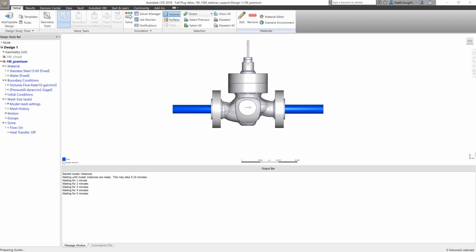Okay, so we are starting to see some questions. So do we need to worry about large element counts, and is there a restriction of RAM? The reality is we already have a really high amount of RAM for the workers on the cloud, and I haven't seen a lot of restrictions on element count, but there eventually would be, right? You're going to run a 100 million element model. It may or may not run on the cloud, depending on the mesh and the solve. You could hit a limit there.